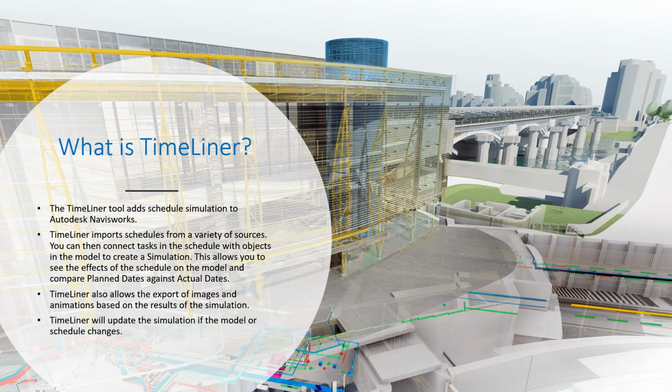So what is Timeliner? Timeliner is a tool that adds a schedule simulation to Navisworks. It allows import of schedules from the most popular applications out there for the construction industry. Once the data is in Navisworks, we can see planned and actual dates and create a simulation based on that. It allows us to export images and animations based on the simulations that we create, and also to synchronize and bring the latest data from those schedules to map to our geometry.